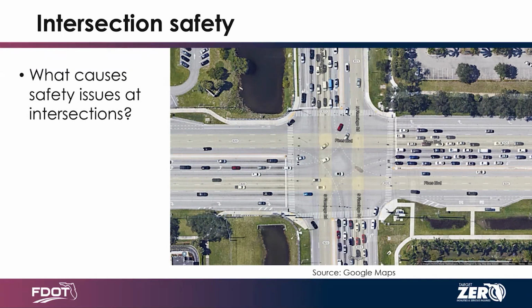Things like high speed, or for example, in this intersection, the crosswalks are really long, so that would be really difficult for a pedestrian to fully cross. I suppose it could be signalized in a certain way to make it more evident, but yeah, visibility, especially with the right-hand turn and that conflict with pedestrians or cyclists. Yeah. Yep. That's great. Billy?